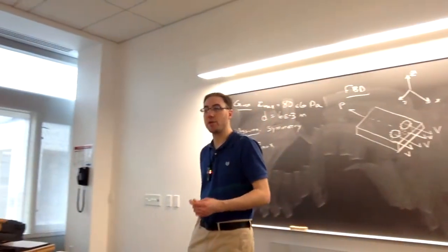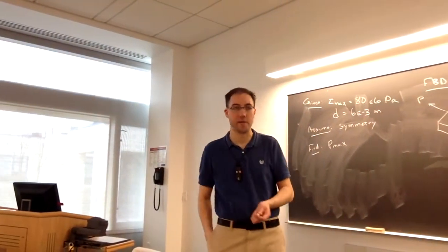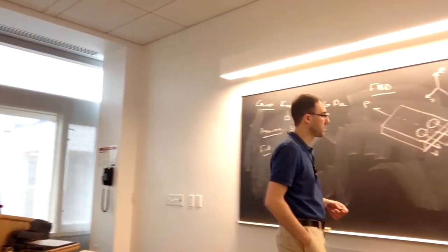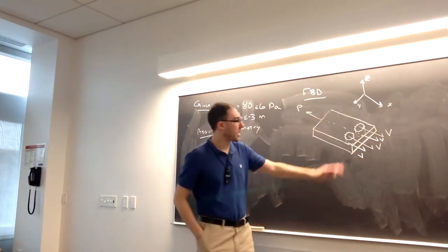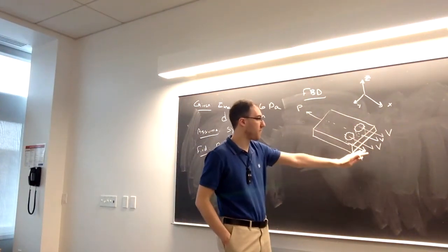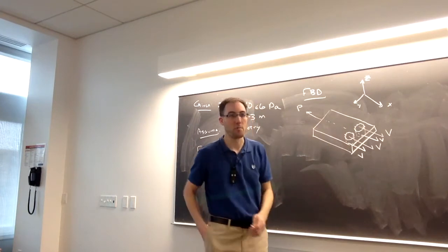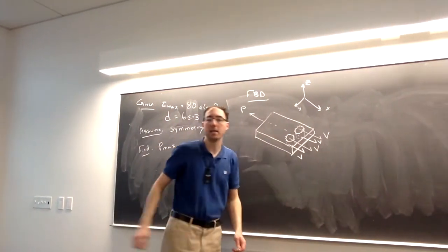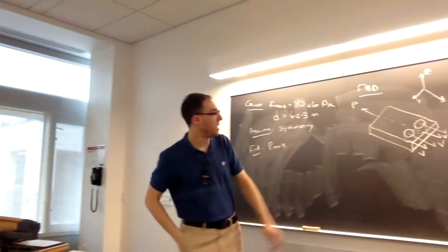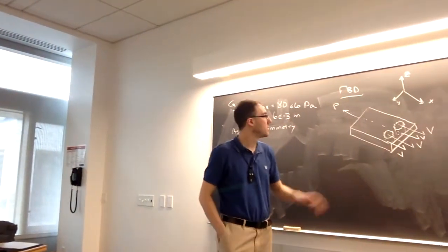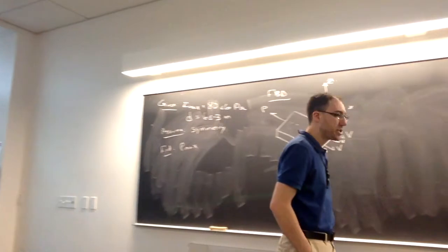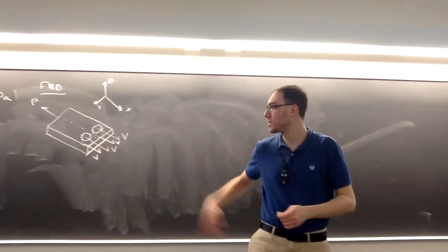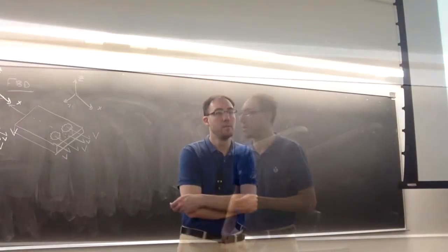Again, because of symmetry, I'm going to assume it's the same value V in all the places. So because I cut through really four surfaces here, all four of these surfaces are resisting this applied load P that I'm applying at the end of this piece of wood. So there are 4 internal shear forces, and there's 1 applied force here.